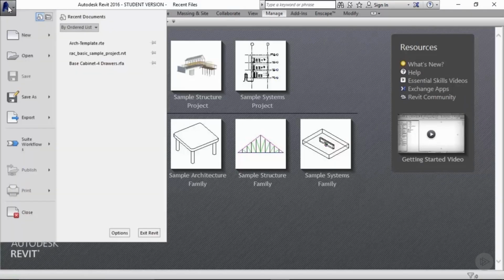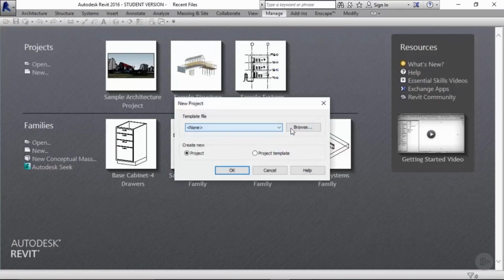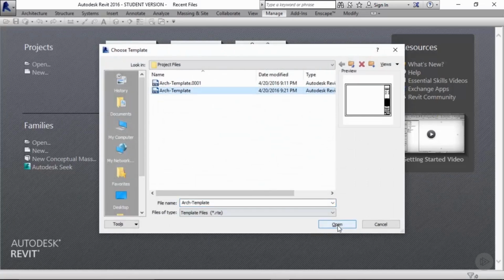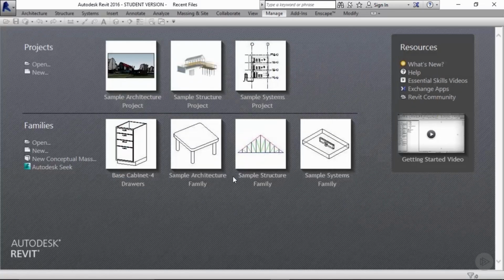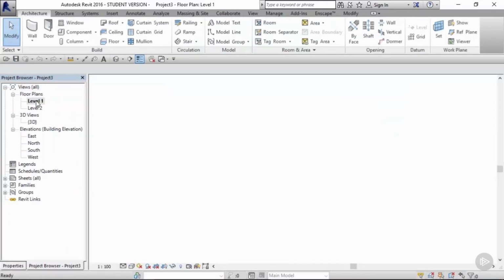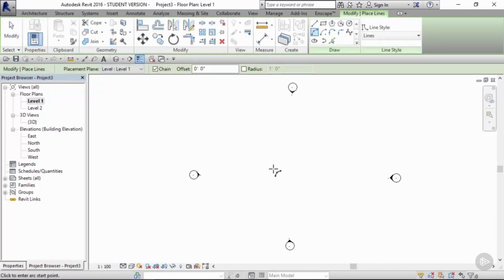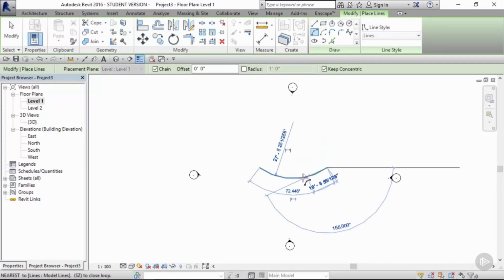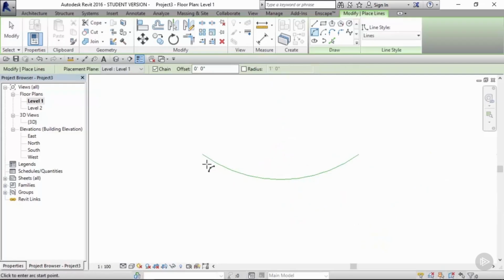To start, our first task is to create a series of points upon which we can base our mast. The objective of this exercise is to simulate what it would be like to create a shading structure in an actual Revit environment. To do this, we'll use a model curve in the Revit workspace to map our mast generation. Beginning with a fresh Revit file, we'll go through the process of establishing a model curve on the first floor that has a simple bend.